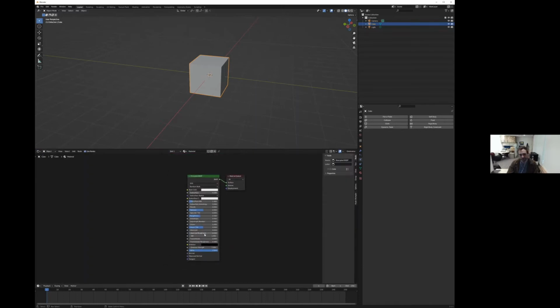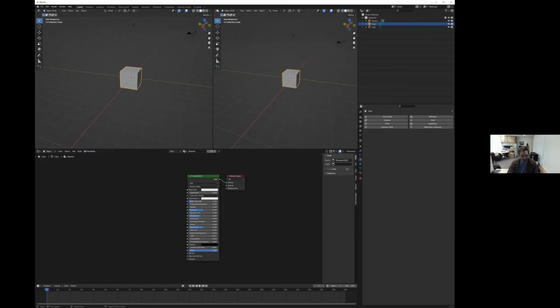So this is a way of being able to maximize your interface and customize it depending on what piece you're working for. To be honest, I don't typically go into here because as I'm going, I'm essentially adding panels like this for whatever piece of the pipeline I'm working on. So if I was, say, doing UV unwrapping, I would have this here. I would be doing my UV maps here, be working with my materials, and I still have access to my property panels and my hierarchy.